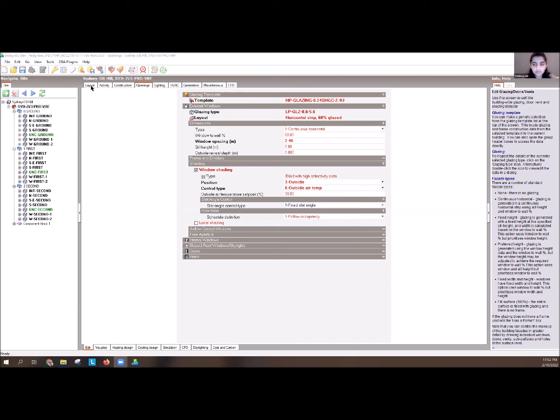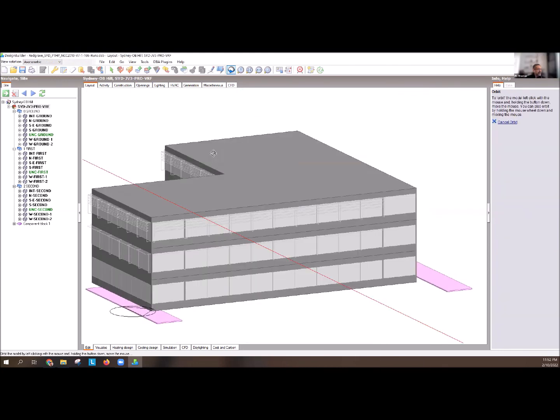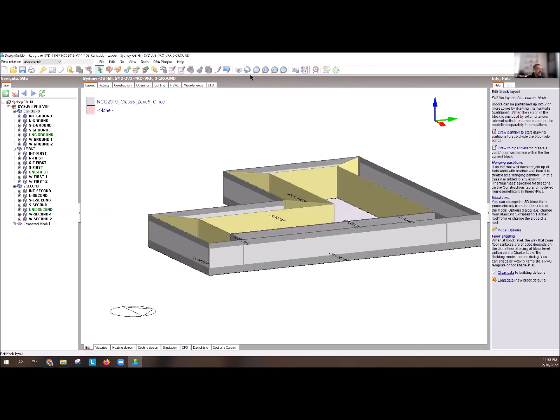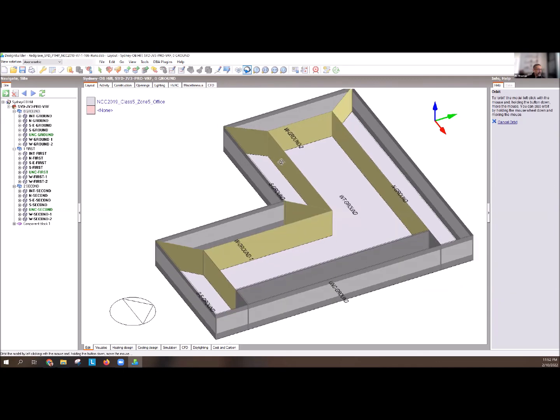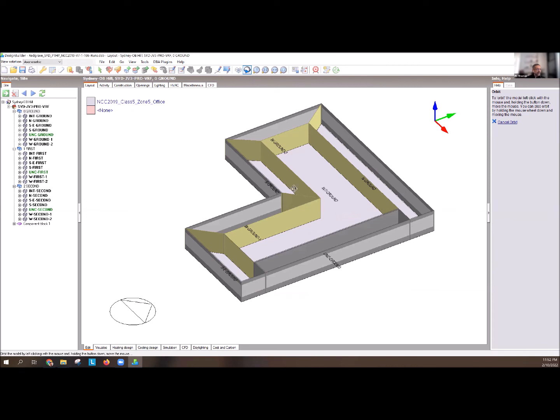So before you run a simulation, you need to tell the energy simulation many things about the building. You are already drawing the building, so you're telling it something about how the building's floor plate is, how you've divided it up into zones. Then in each zone, you are saying, what is the construction material and the windows? So then you're talking about the heat transfer, the building loads, as it's called. And there's quite a clear explanation in that lecture that I've given for all of those things.